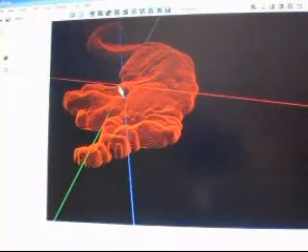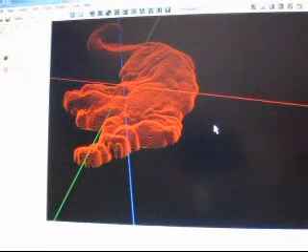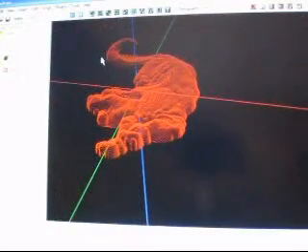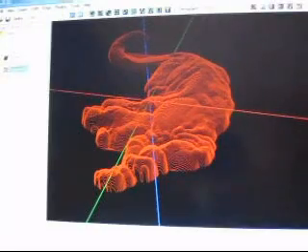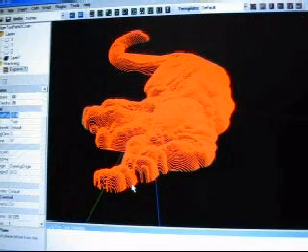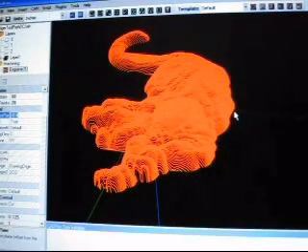And the toolpath itself is going to do that. Because when we're done writing this toolpath, well, you'll see how we're going to fix that next. So we're tricking the system into doing what we want it to do. Basically, you set your clearance plane to your floor depth now. And then we'll go and modify the code, and it's really easy to do. It's a pretty automated process.